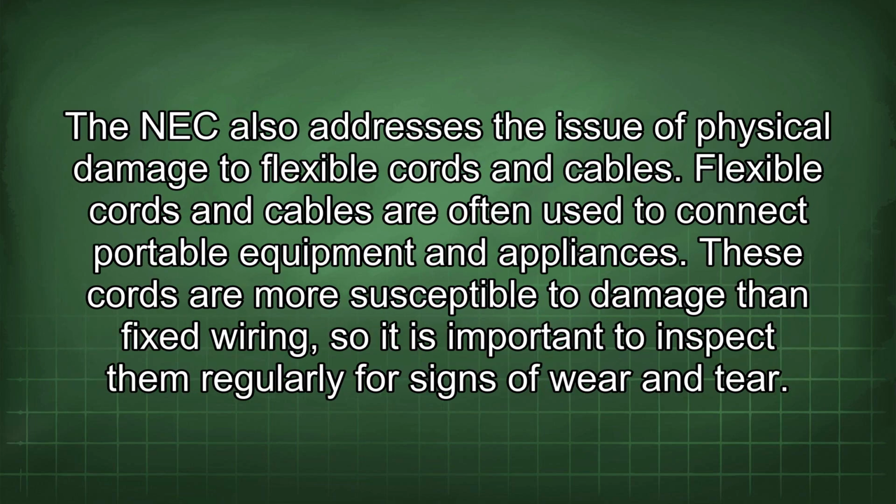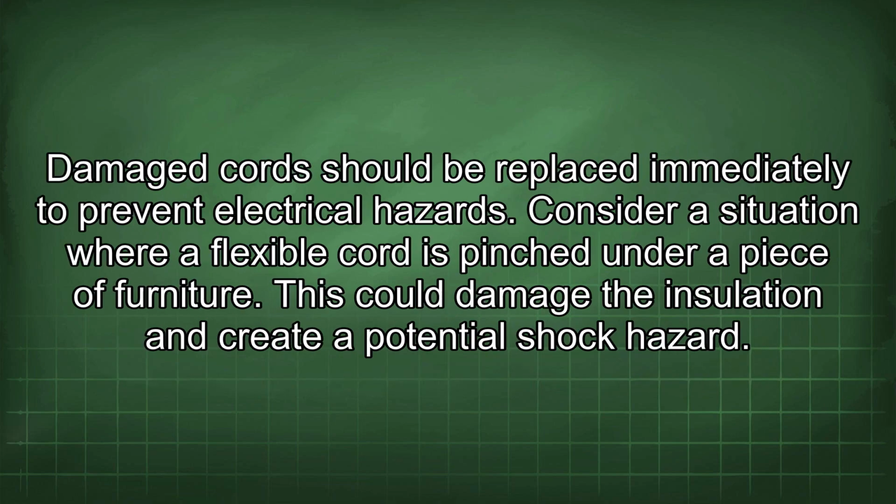The NEC also addresses the issue of physical damage to flexible cords and cables. Flexible cords and cables are often used to connect portable equipment and appliances. These cords are more susceptible to damage than fixed wiring, so it is important to inspect them regularly for signs of wear and tear. Damaged cords should be replaced immediately to prevent electrical hazards.